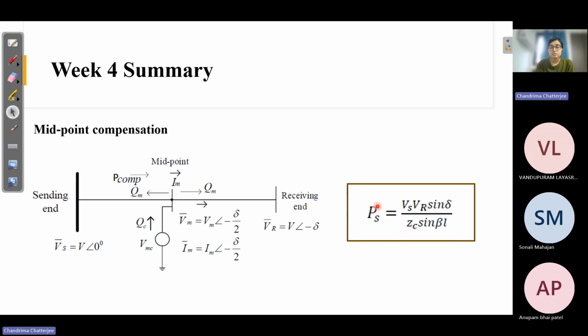And also the active power doesn't remain the same. Active power also changes. Now you may question, we are doing reactive power compensation, then why does the active power change? The active power changes because the voltage here will change. Without compensation, whatever voltage you have here, after compensation, definitely the voltage will change, right? Because that is our intention, to prevent the over voltage or under voltage over here.